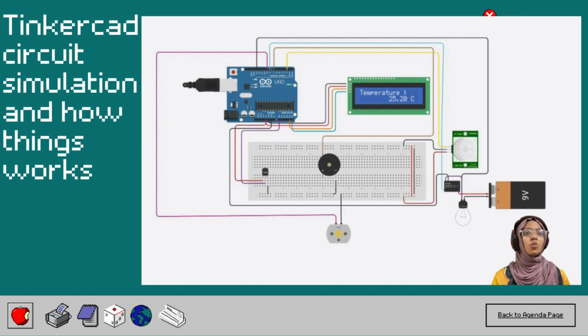Next, we make a slight adjustment to the temperature, which is now 62.56 degrees Celsius. Now, the temperature has exceeded the maximum allowed temperature, which is over 50 degrees Celsius. The system activates a high temperature warning on the LCD display. So now the cooling system is activated.